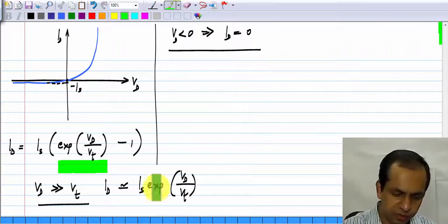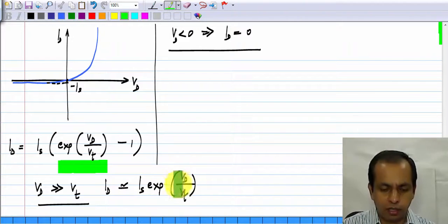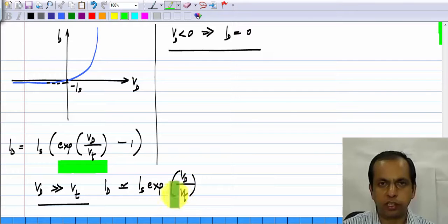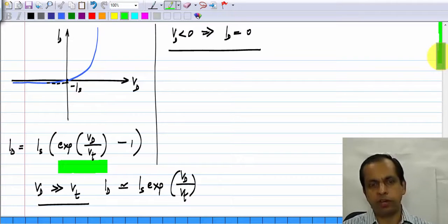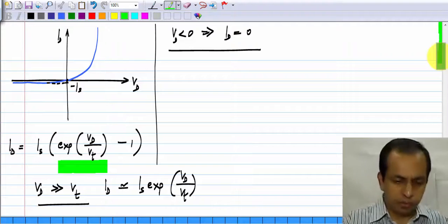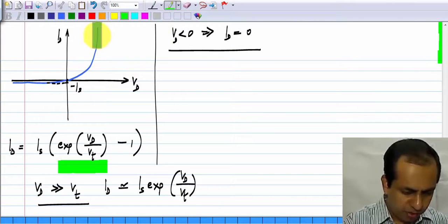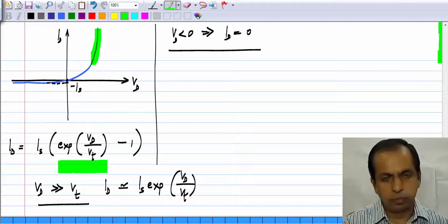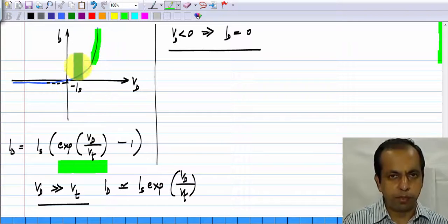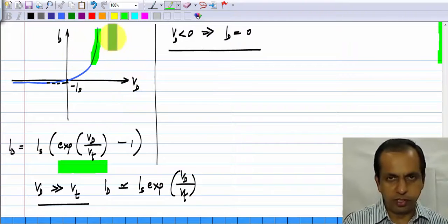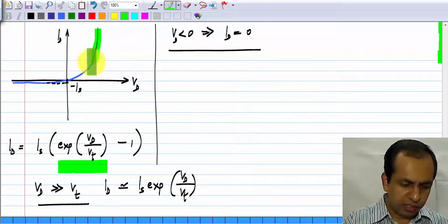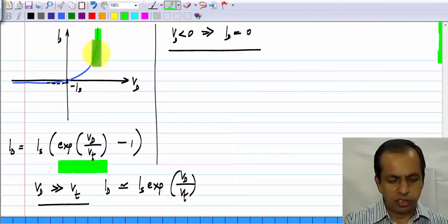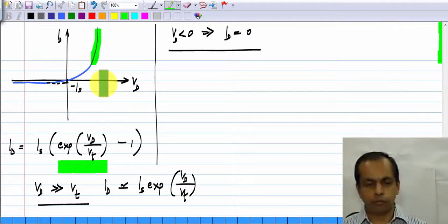Of course, we are still left with a nonlinear equation, and this is useful for certain classes of circuits, but still even for simple arbitrary circuits you have to solve nonlinear equations, and we would like to avoid that for hand calculations. So, the next approximation that you see is that if you look at this part of the curve, it is quite steep. I am plotting ID versus VD and the curve is very steep. So, what you can say is that in this part of the curve the diode voltage does not change much. It of course changes.